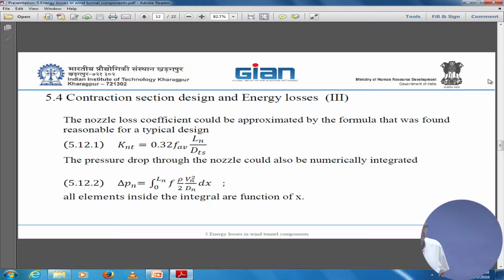Actually, what you want is for the turbulence that is created by the wires from the first mesh to decay somehow. You don't want extra work because you have a screen there. So you wait till the turbulence that is created by the first mesh decays, and so forth.